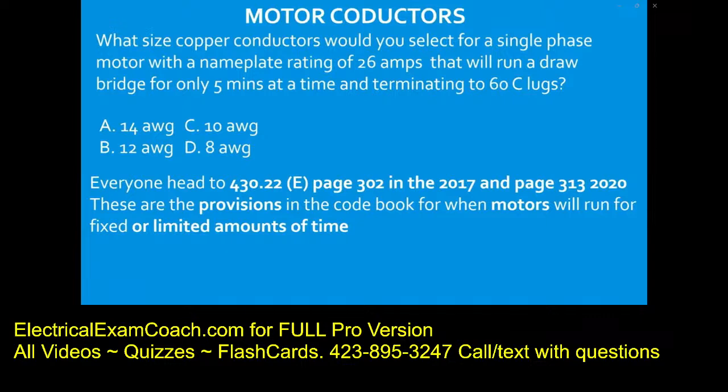For these ones we are going to go to table 430.22(E). It's usually on the next page of your code book. So whether you're in the 2017 or the 2020, it's typically the next page over. When we get to table 430.22(E), let's look at it now, starting with the black bold heading. It says duty cycle service. Pretty sweet. Now using our black bold headings, top to bottom, left to right, starting on the left-hand side is going to be our classification of service.